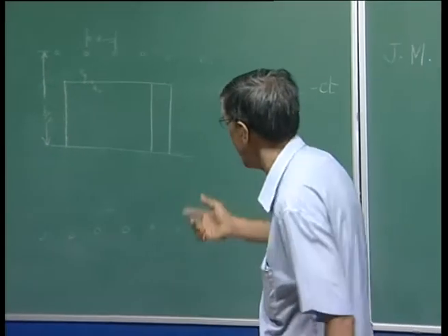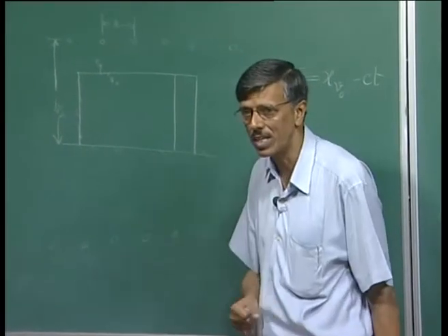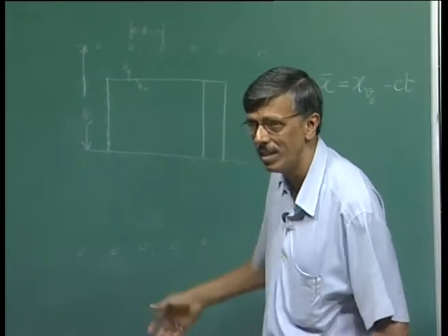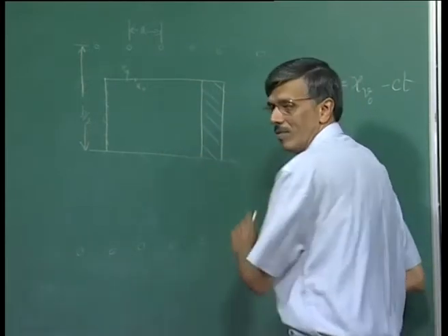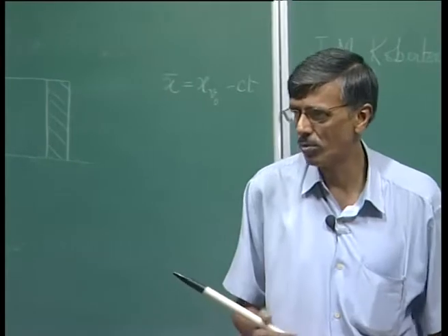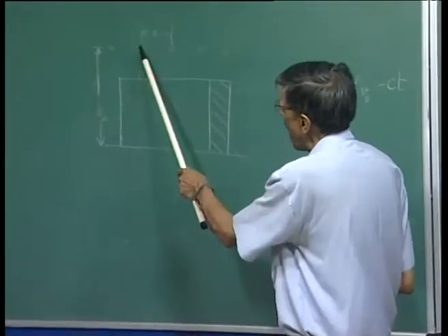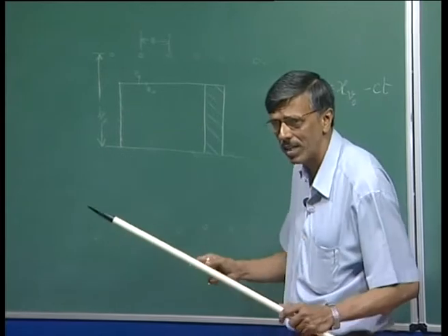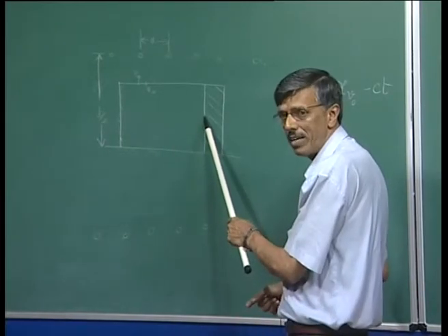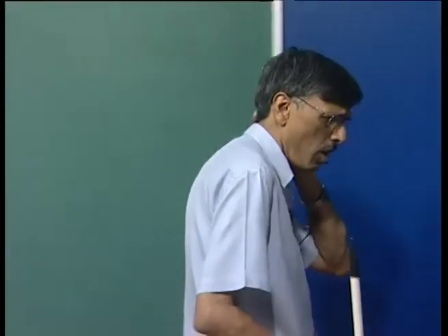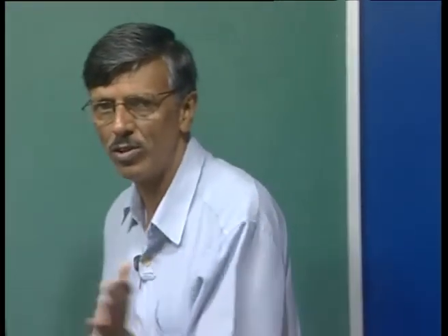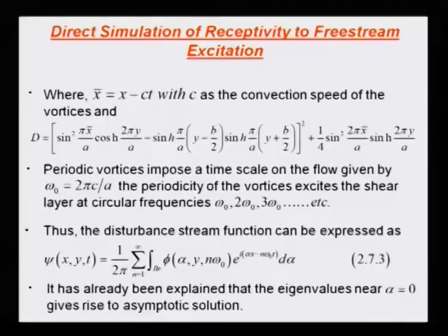So we have to give some interesting boundary condition that we are talking about, and we have already said that in this buffer region, what we do is those disturbances plus this, all of the sum together will be decayed from some finite value to almost negligible value. Okay. Also, despite that, whatever may be the remnant should be allowed to pass out cleanly. So we'll talk about those boundary conditions shortly.